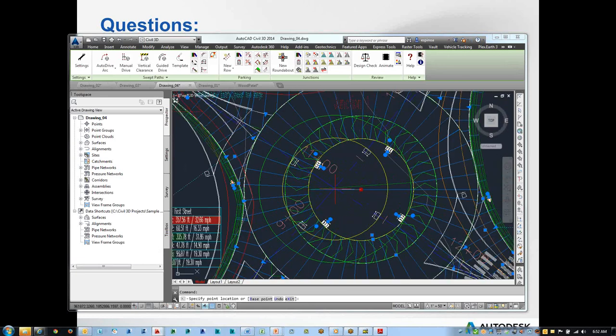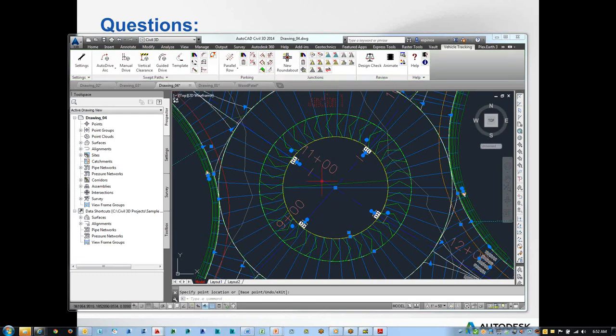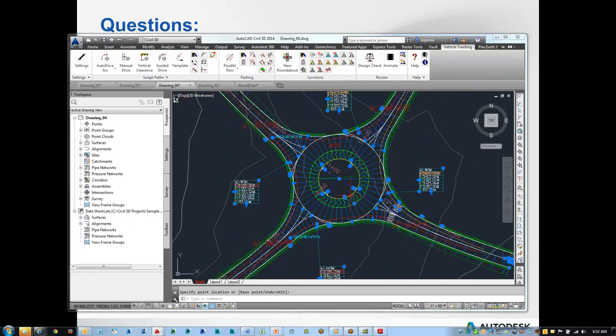So if I were to place that at, and I'll just eyeball the accuracy for the moment, and if my corridor is set to rebuild, which by default this one is, everything gets rebuilt right on the fly. So thank you for asking that question, something I probably should have done. So after the fact, as far as making adjustments, not a problem. Things will dynamically both redesign in 2D and ultimately rebuild in 3D in the corridor. Thank you.